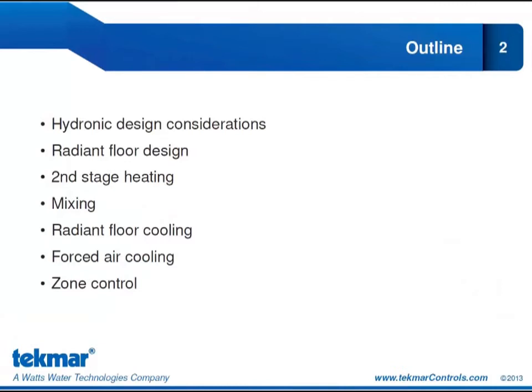Next, we'll talk about radiant floor cooling. And we'll introduce what the limitations of radiant floor cooling are. Remember, we can only address the sensible cooling load. We can't remove humidity with a chilled floor. So we'll be looking at what we need to do for a well-designed cooling system. We can't rely on radiant floor cooling alone, but it certainly can provide a large base load amount of cooling that'll reduce the load on the forced air system.